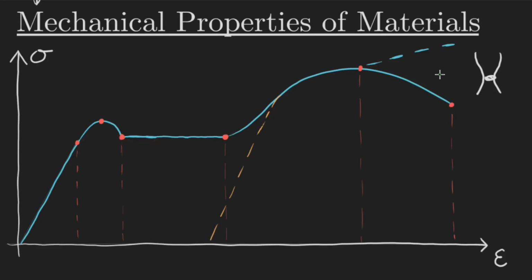You also have things called brittle materials, whose diagram would just look something like this. Boop, right there, it fails. So you get this linear region, more and more and more, and then it just breaks. There's no yielding. It doesn't lengthen. It's kind of like the difference between a hard taffy and a taffy that you heat up, and you can bend it a little bit.